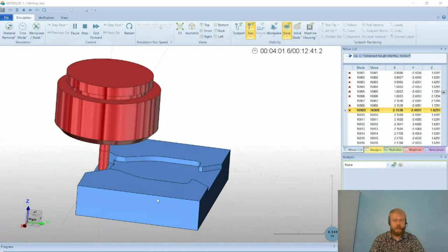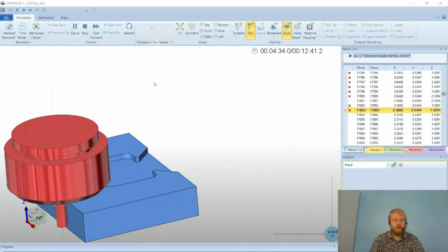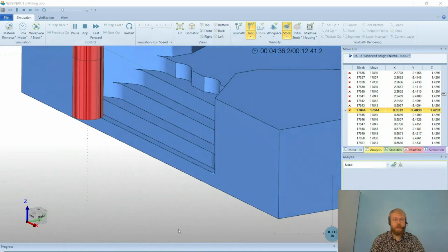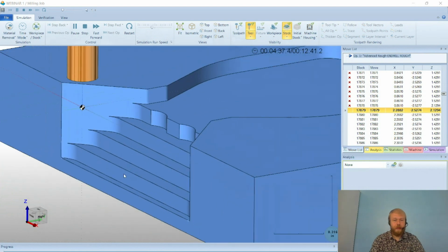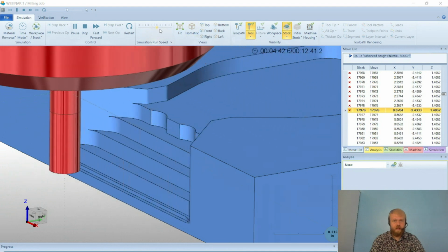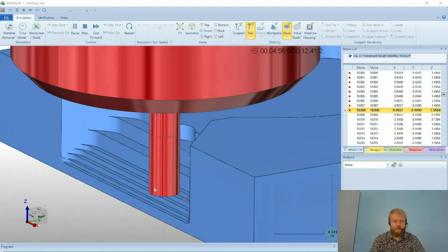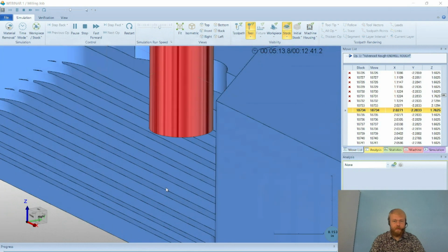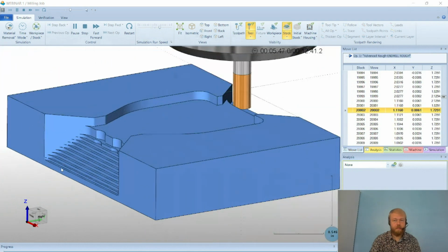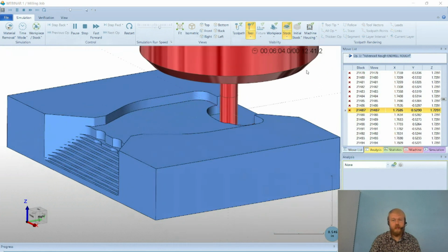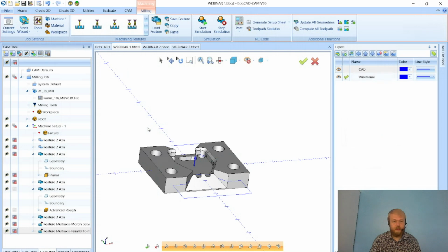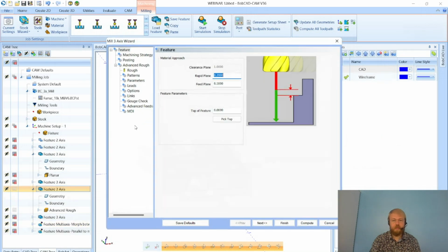And now on the other side here, it goes down 100 thou. And then once it goes down to the bottom here, you'll see it'll come back up doing an additional couple of passes at each depth here. So it'll remove more material in between the 100 thou depth of cut for each one there. And that option is set under the advanced rough.